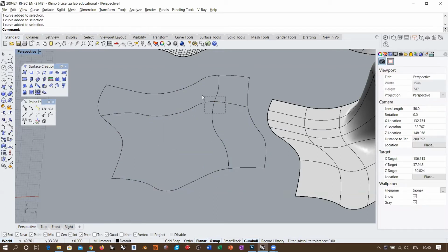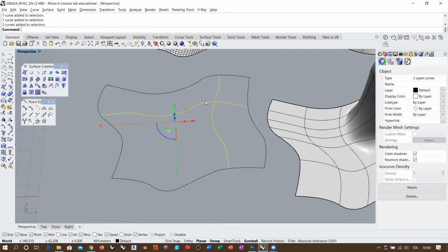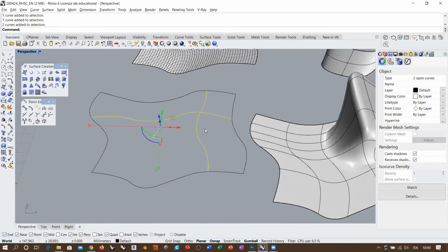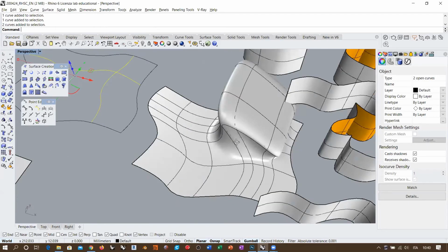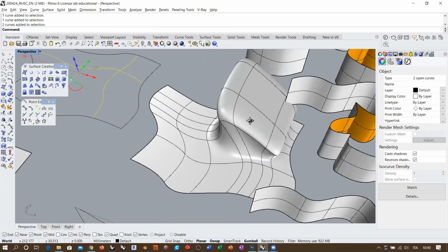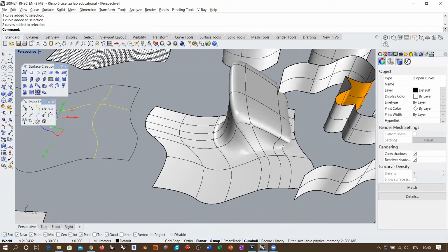So if I increase the height of this curve in this area, the surface will start from here and tend to reach the height of this section. So this is not enough. But anyway, let's consider this is enough. What's the problem in this case? Well, if you take a look at any of the NURBS surfaces that we have created, all the isocurves always intersect along the surface and lie on the surface.